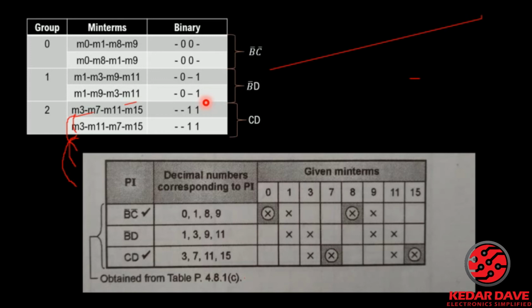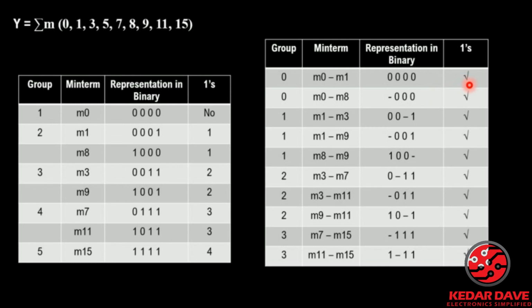Now what we need to do, whenever we are doing this elimination technique, we just put on this right mark onto the places of that particular min terms. If we are doing over here, then we will put right check mark, check mark, check mark, right? So this way, these are the prime implicants, and they will appear in the simplified Boolean expression of the particular Y function, right? So here you can see there are no such terms in the table, but there are 3 such terms